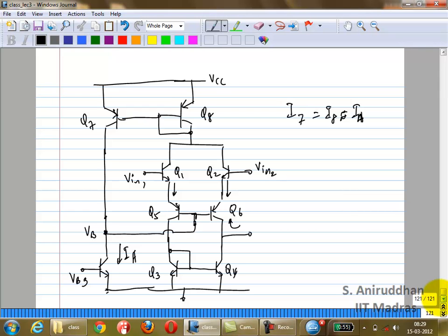What kind of asymmetry? Well, I think any circuit is symmetric to more sensitive to asymmetry. So what makes this particularly more sensitive to asymmetry? The current through each of the transistors is more sensitive to the emitter voltage here than the collector voltage.